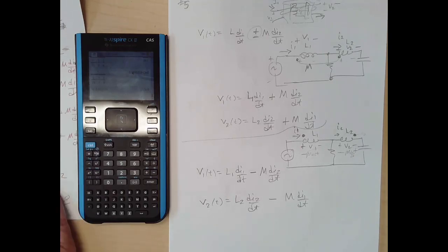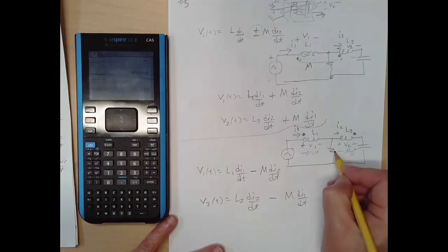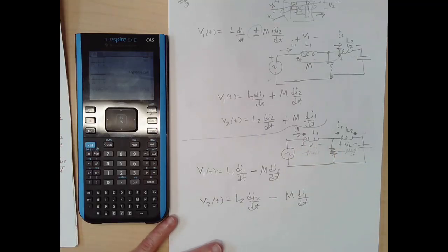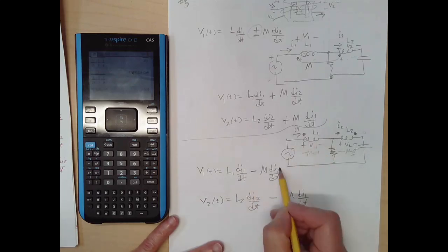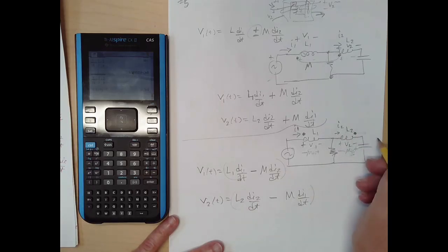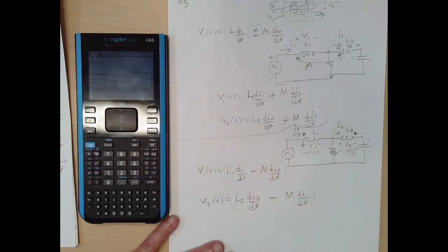Well, hopefully that's good enough. Hopefully that makes sense. If we were doing KVL, probably with voltages, we could use these voltages in our KVL equations. These two terms would be the voltage V1, and these two terms would be the voltage V2. For the capacitor voltage, I is C dV/dt, so V is the integral of I dt, and the voltage here is IR. We could do KVL equations, do some solutions, things like that.